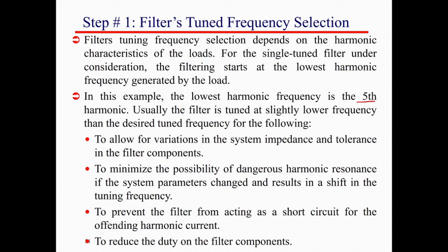Of course, as we have discussed already, the filter normally is tuned at a slightly lower frequency than the desired tuned frequency to allow for variation in the system impedance and tolerance in the filter components.